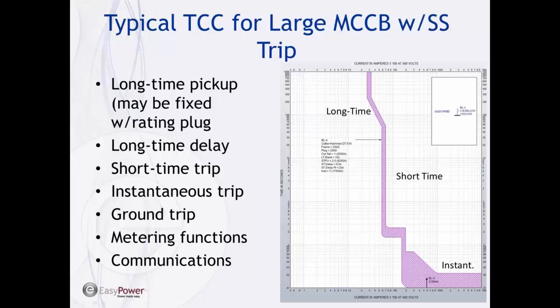This particular breaker has a little bit of a range where the instantaneous trip is speeding up as the current increases. And I turned off the clipping so you could see what that looks like at the very high levels of fault current.